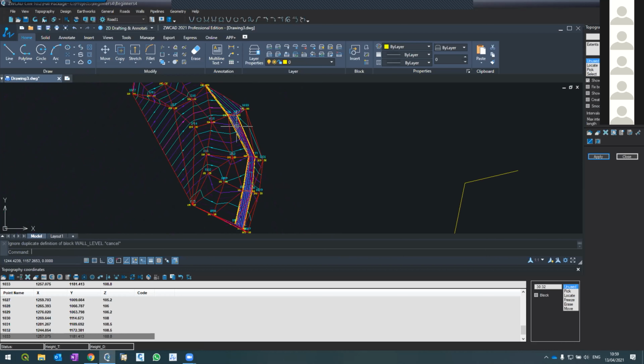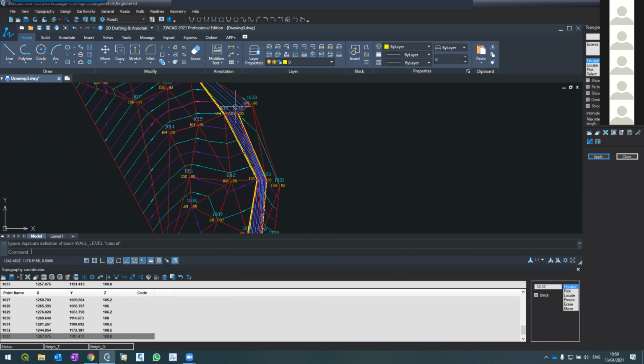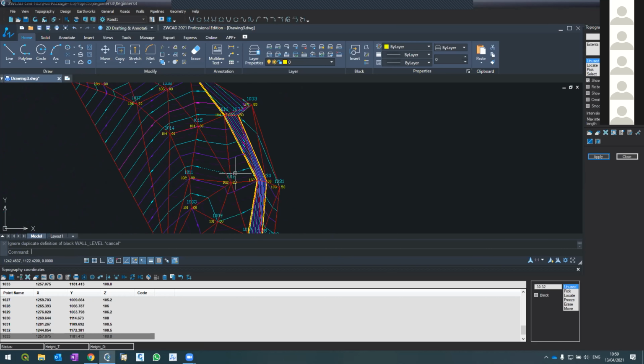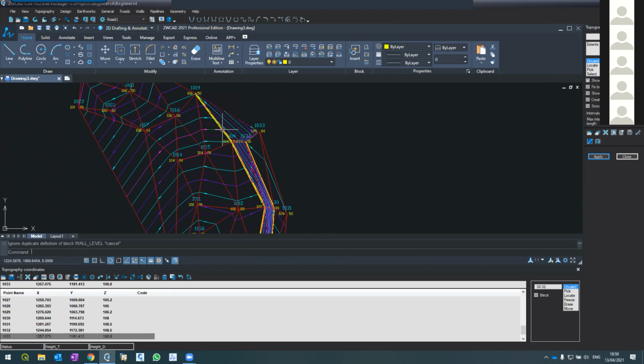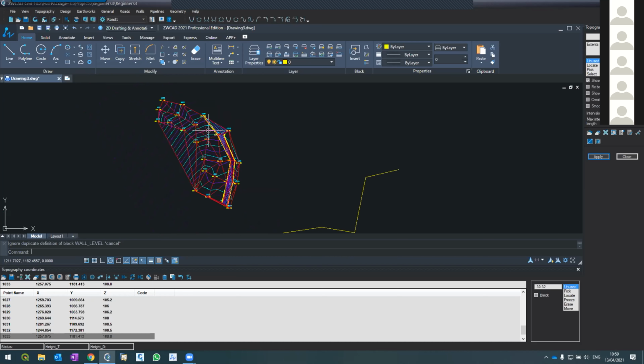In fact, let's summarize the issue of breakline. Breakline is a mathematical problem, where 2 points are interpolating and we don't want them to interpolate. The solution is to create a breakline, which breaks the interpolation. For the software, a point on one side of the breakline does not interpolate with the other side. The interpolation is to the breakline and from the breakline.